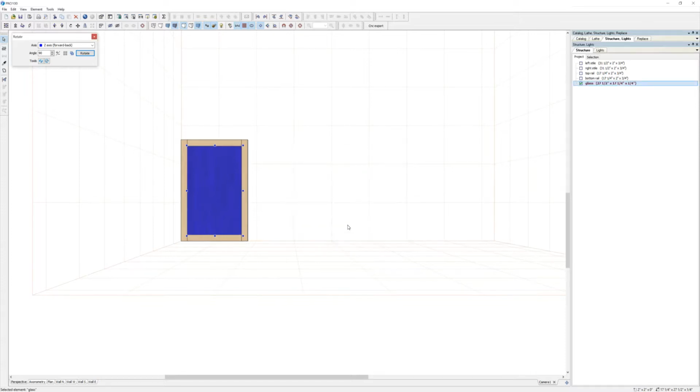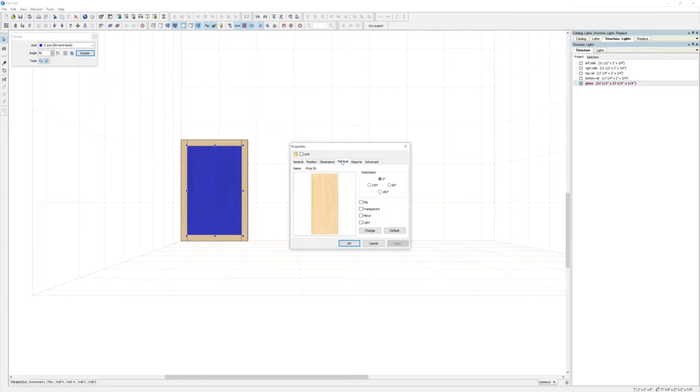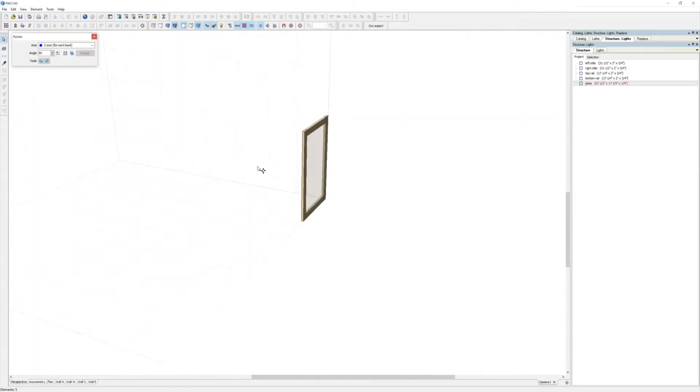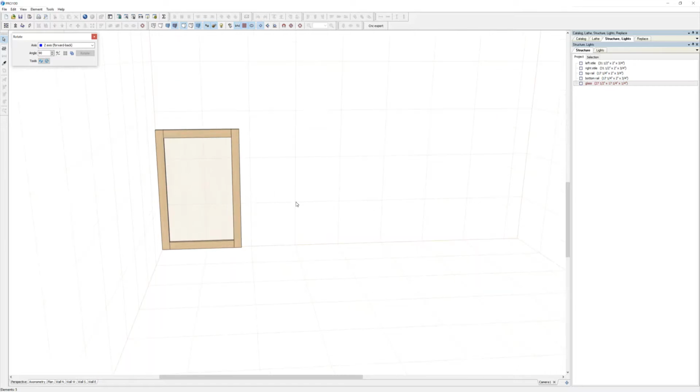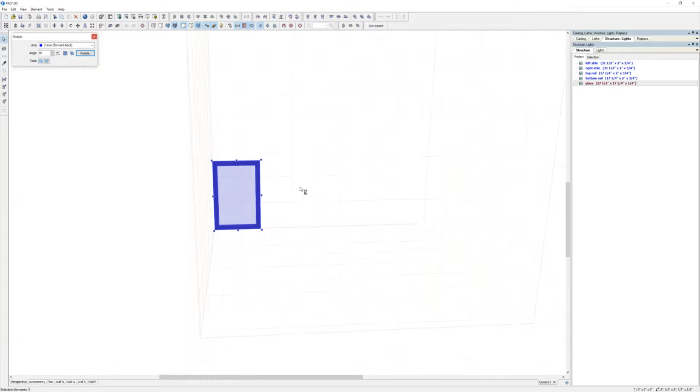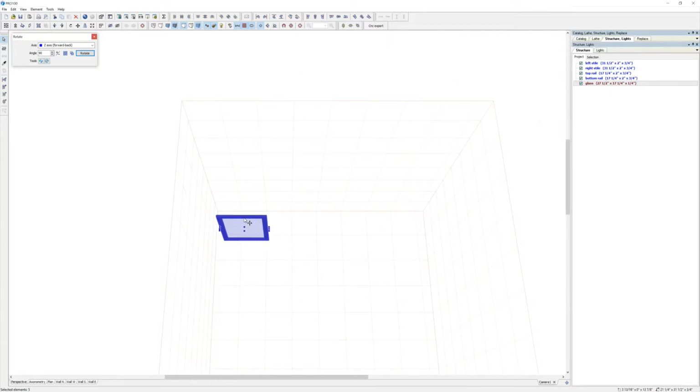All right, now I'm gonna make it look like glass because right now you can't really see it. So I'm going to material and make it transparent. Click OK. You see, you can see through. I'm gonna come back to this a little bit later on how to make your glass look more real in any project. Now we're gonna select all and pull it out a little bit, then rotate in the y-axis, or I can use this 90 degrees.